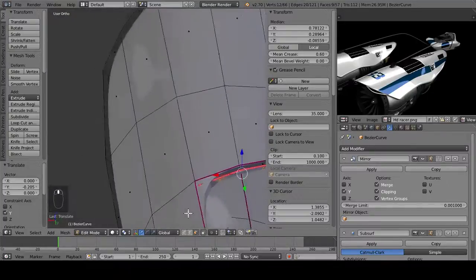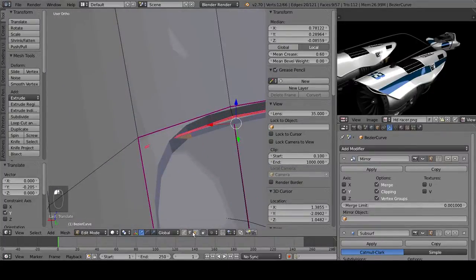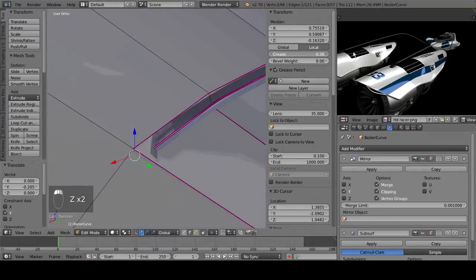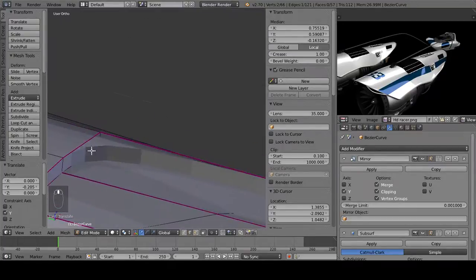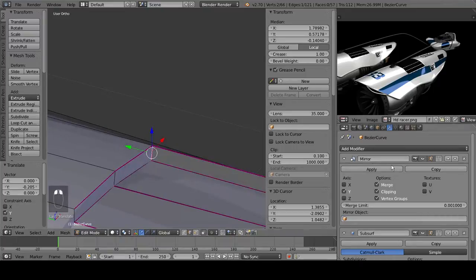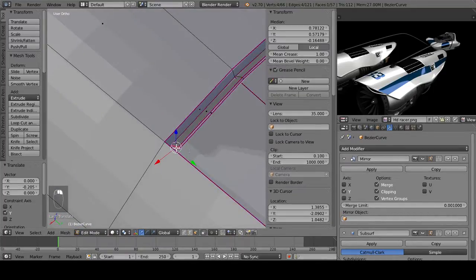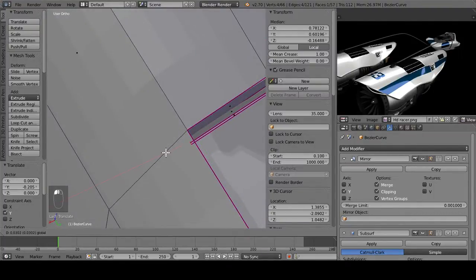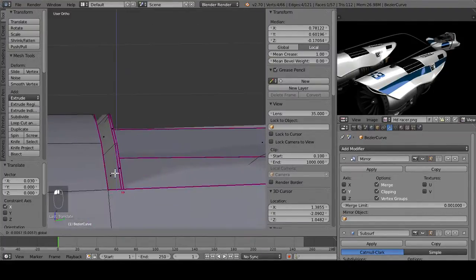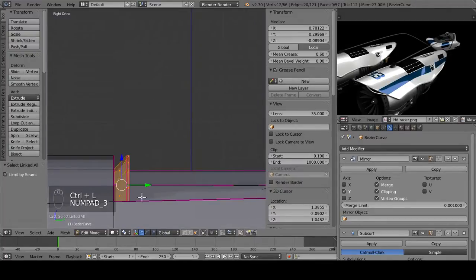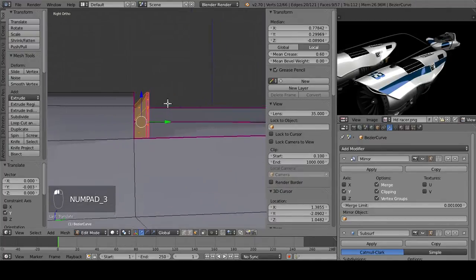And this is melting through here, you can see, and that's just because this inner corner has not been creased completely. So we will just do that now. And then we have to take that face again and just line it up just a little bit. So we can Control L, select the entire thing, move to the side view, line it up nice where we want it.